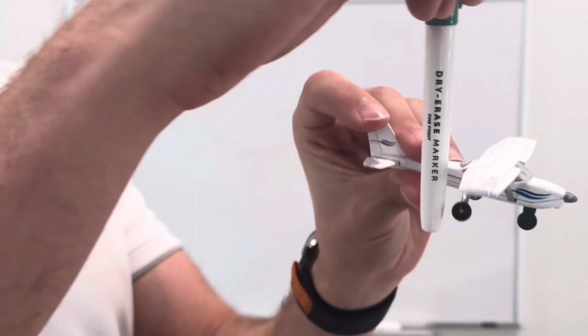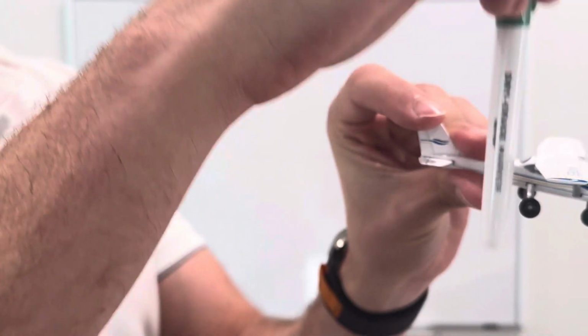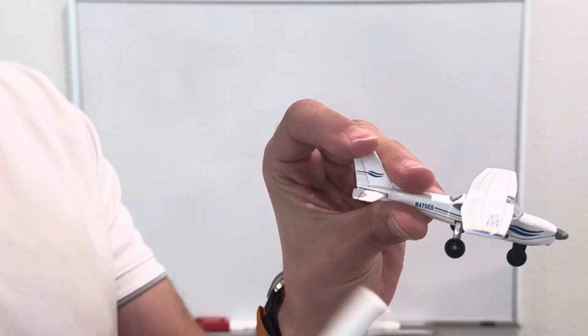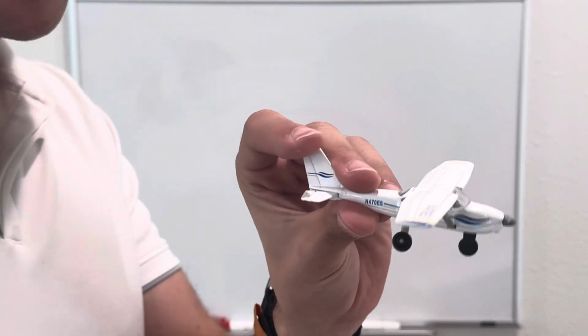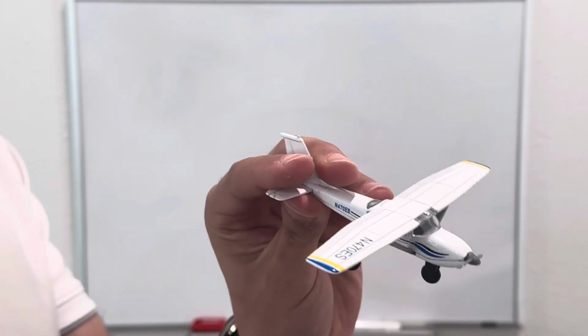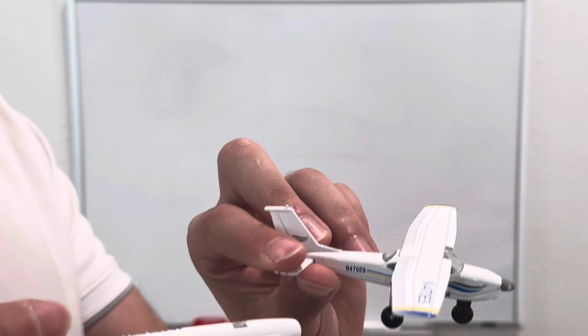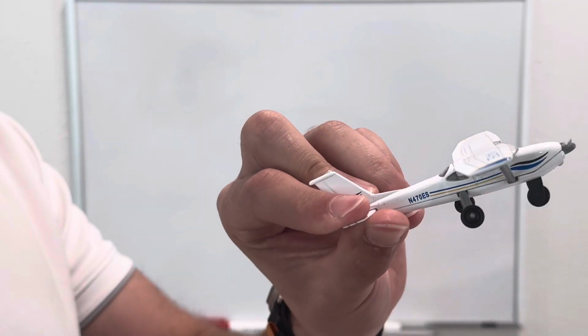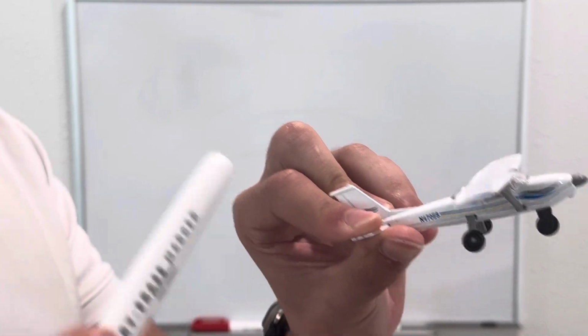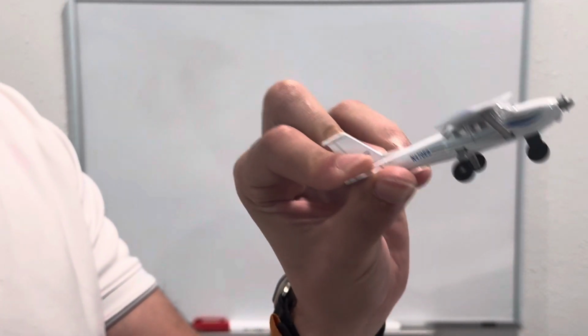Another one is weight. That is a downward force on the airplane caused by gravity. With weight, we can talk about load factor, which is a principle of flight. Through load factor, we can discuss how at a higher angle of attack and an increase in weight, we have an increase in load factor and higher stall speeds.